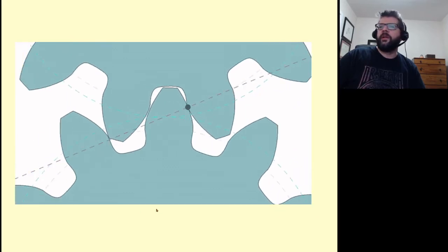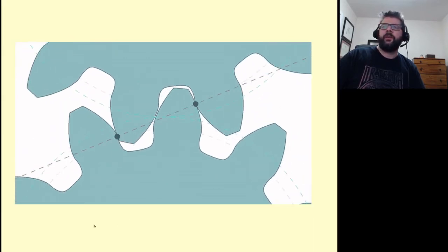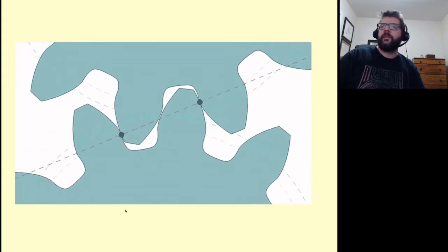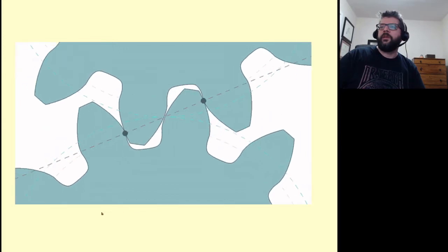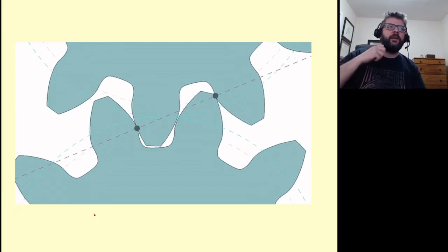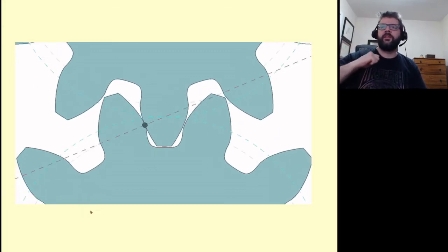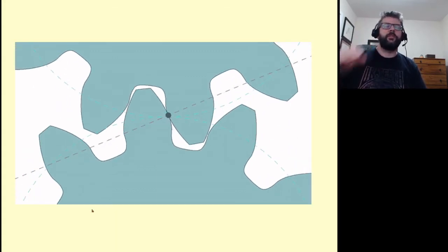This next one is an example of how these get generated. One way that we can form gear teeth is by taking a rack and rotating it, using it to cut the gear tooth as it moves around.